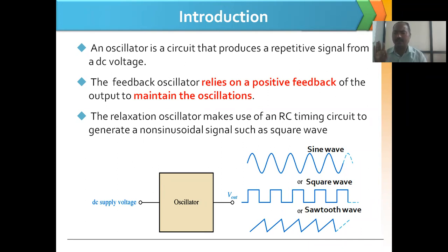I'll tell you an example related to the same. In an older period, if we used an amplifier with a mic, sometimes the signal strength would go up and down. Today's amplifiers don't have that problem because they use a different technique, right? Sometimes the sound would increase, then decrease. This happened in the older period, because positive feedback was in use. With development, today they use negative feedback.